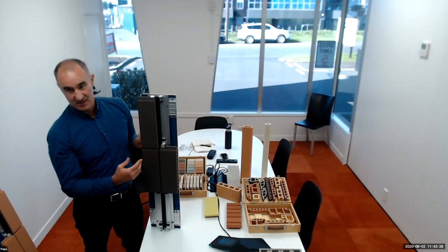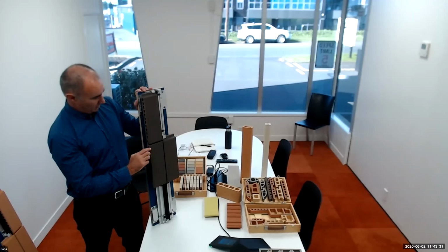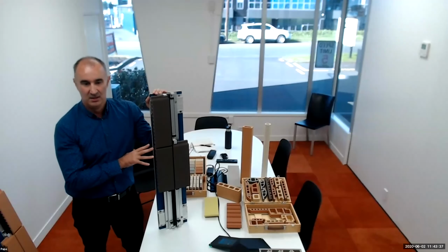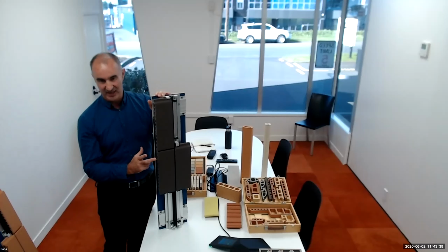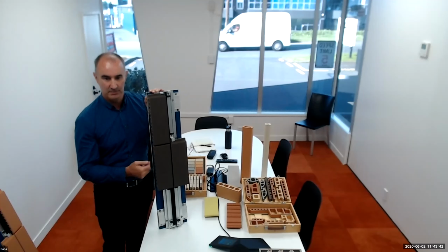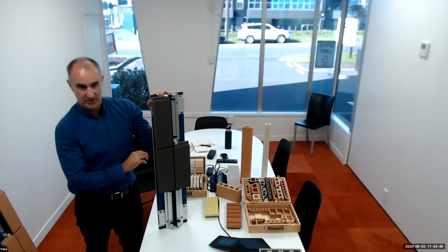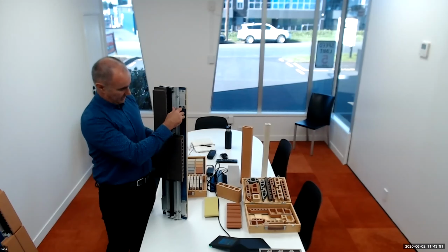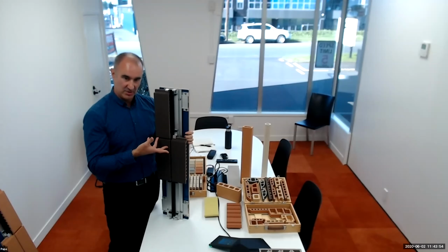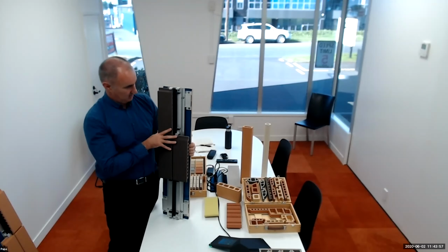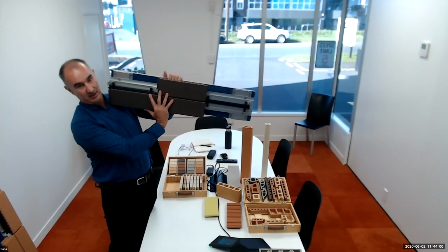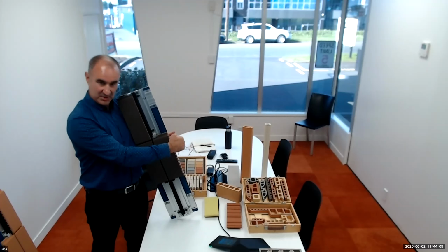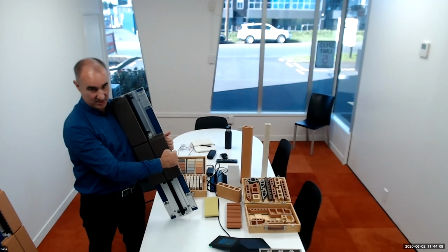And then the rest of it is exactly the same as what I just showed you. The open joint allowing airflow and everything through there. So that's the typical method for New Zealand. Obviously, the benefit is you don't have as deep returns with your box out windows and that sort of thing. Don't need to be as deep. And also if you wanted to run the tiles vertically in a format instead of horizontally, it's basically just doing it that way. So you have your rail at every horizontal joint. The only difference is the clips then clip in, go from here into the cavity.